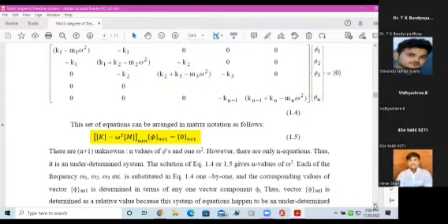As far as matrix K is concerned, it is known to us because we know the size of each beam, each column, each wall. We also know the material, whether it is concrete, steel, or mixed construction. So we know the modulus of elasticity, the moment of inertia, the area of construction, and so on. So stiffness K is fully known to us. Similarly, mass. Since we know the size of each element, we know the density, therefore we know the weight and therefore the mass of each element in our building. So K and M are fully known to us. What is unknown is n values of phi and one value of omega, which is the frequency. So there are n plus 1 unknowns in total.